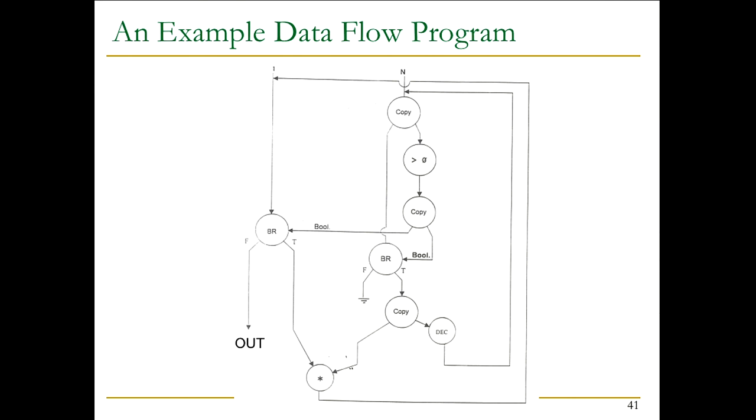And at the end, they reorder the instructions such that the programmer sees the sequential order. That's how you get the high performance. So basically, at the ISA level, you're still von Neumann, but internally, you're data flow. That's called the restricted data flow. And all high-performance out-of-order engines operate this way today. This engine here operates this way. All of Intel processors are that way.